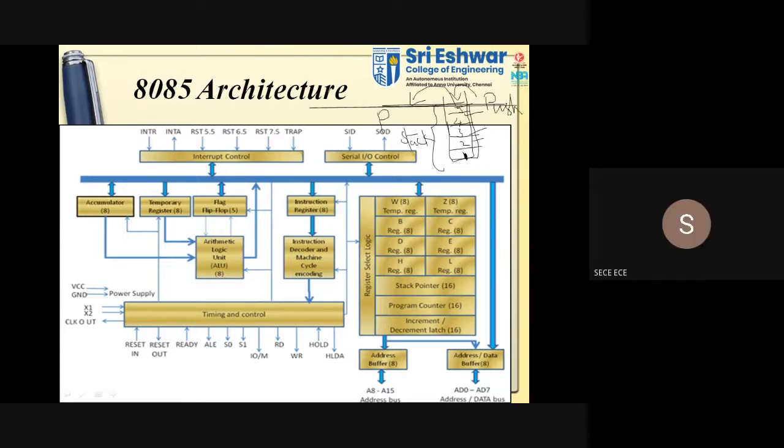Pop, ma'am. Good, someone has answered. Push and pop instruction. Super, Harinikesh. So the push instruction is used to put data inside the stack. The pop instruction is used to retrieve the data out of the stack. We have a pointer on the top of the stack which shows the empty place. That is said to be the stack pointer. On the top it represents your empty space in the stack.